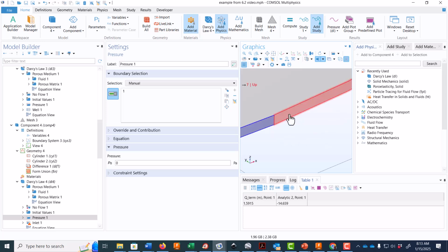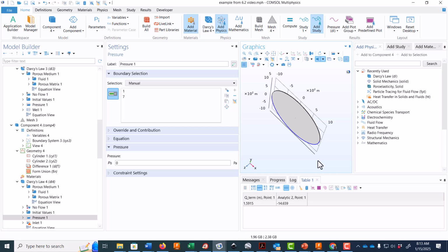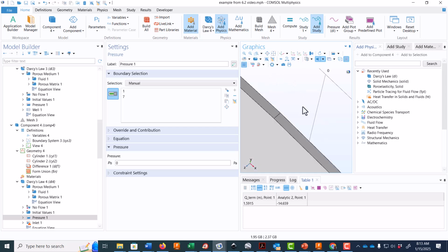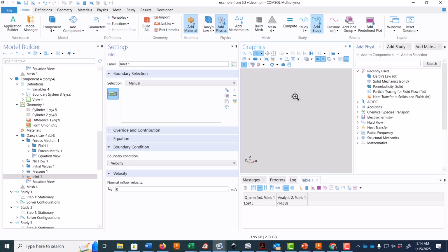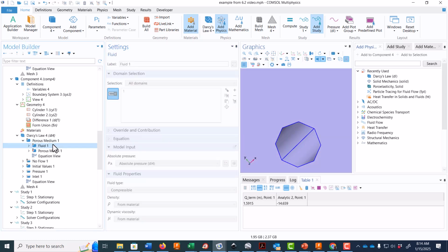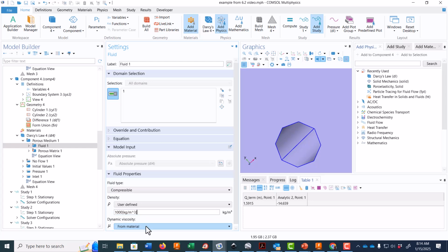We've got to make sure to hit all four of the outer sides. They're kind of thin in this model, so we've got to select all of them, and we see all four sides there that have been selected. And then for the inlet, we have to do the same thing. We have to zoom in on this small hole, and we have to select all four of the inner sides of that hole, kind of rotate back and get that last one. There's four, and then we're going to specify the flux as well flux.